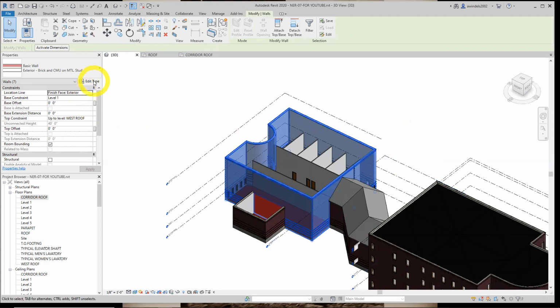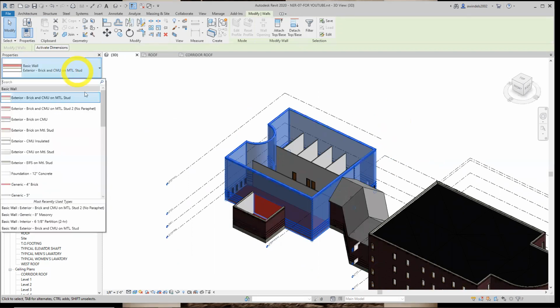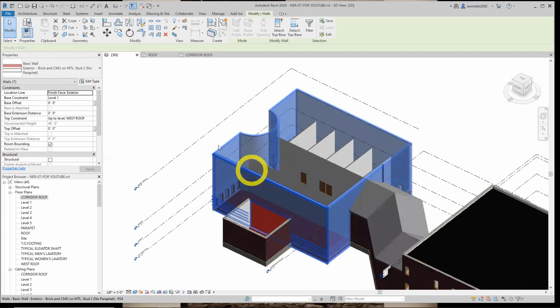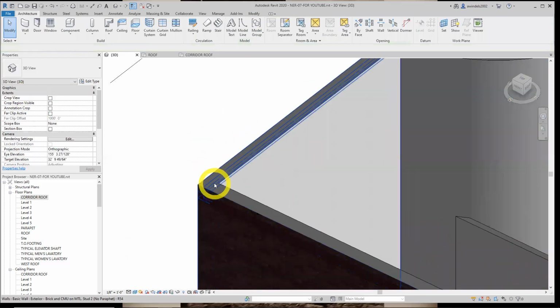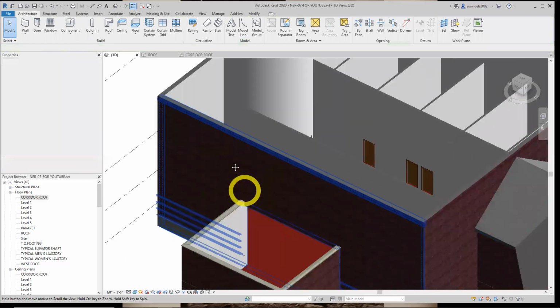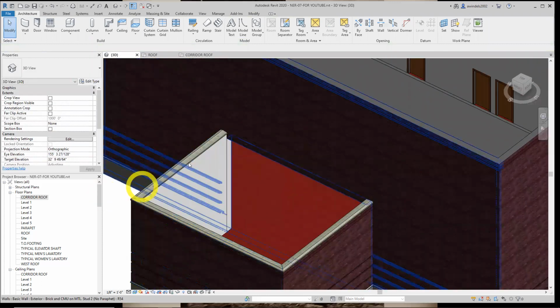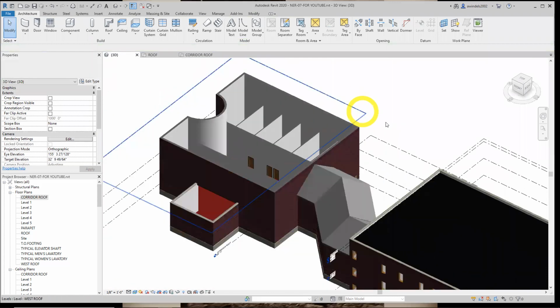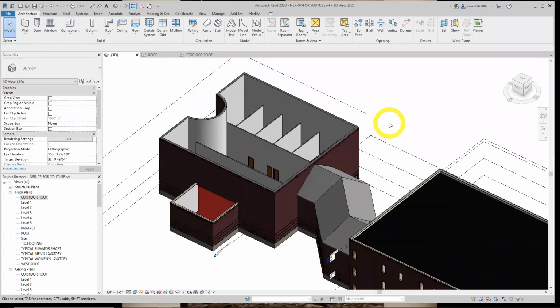We're going to change their type here because we already made it to the no parapet, so it meshes well with the top, because this isn't going to be a flat roof top. So we're going to have better roof meshing if that parapet's not on. I just changed them. You can see it's off now, right? It's still on here, this little short area. It's coming in handy to have the right types ready to go. Let's continue to building the slope roof.